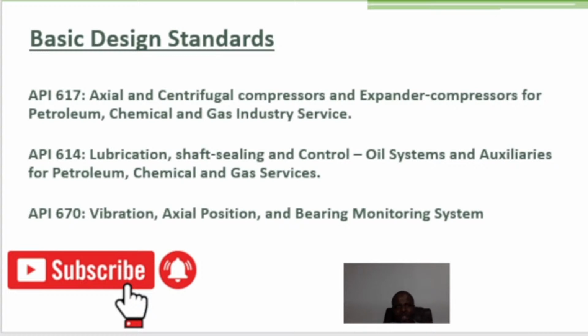These are the various basic design standards that you need to be familiar with as far as centrifugal compressors are concerned. For axial and centrifugal compressors, and expander compressors for petroleum, chemical, and gas industry service, the basic design standard is API 617. Same way you have API 614 for lubrication, control oil systems, and various other auxiliary systems such as steam systems. So shaft sealing is also covered under what?